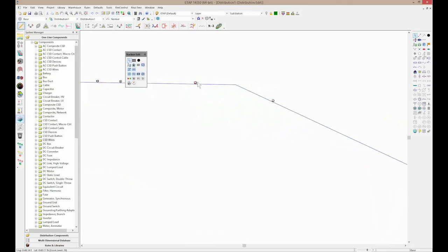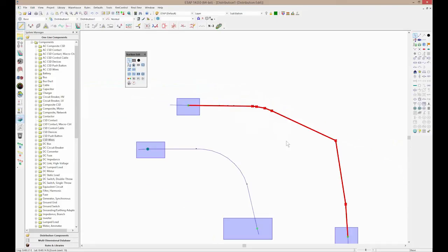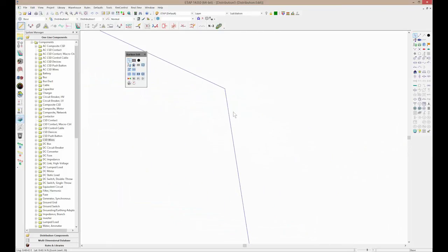One other neat feature that we have inside the geospatial diagram when we are editing the model is I can simply build things with very odd bends, and obviously we all know that railway lines don't bend in this manner, they curve. So I can add points into the system like bend radiuses, and then ask the program to reshape the tracks in a more appropriate manner.